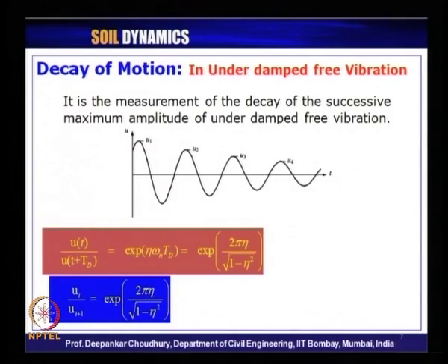of motion. So, what is decay of motion? It is the case only for the underdamped free vibration. In the case of underdamped free vibration, the response of the system, that is the displacement profile with respect to time, we have seen it is like this: a harmonic function with decaying magnitude. These amplitudes keep on decaying with respect to time or with cycles, because of the presence of the exponential decay function in the solution.